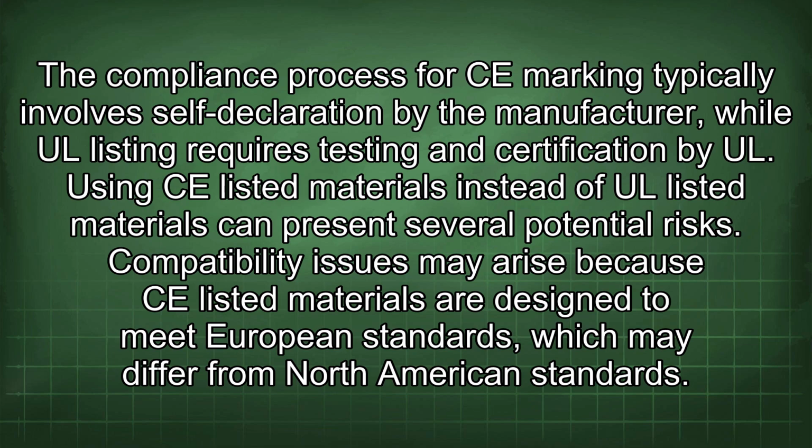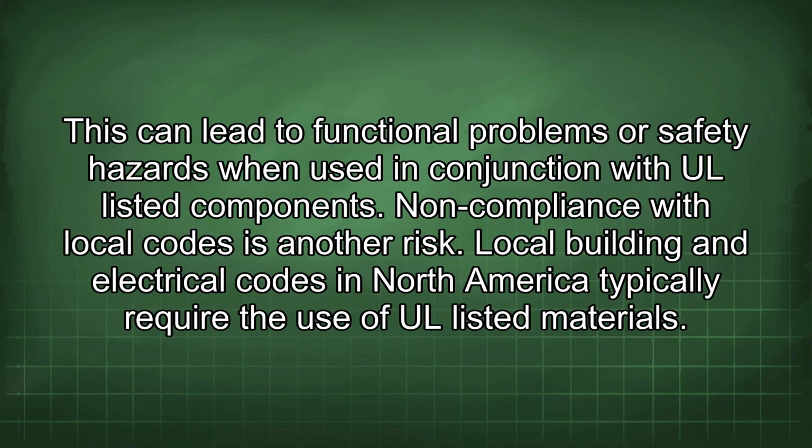Using CE listed materials instead of UL listed materials can present several potential risks. Compatibility issues may arise because CE listed materials are designed to meet European standards, which may differ from North American standards. This can lead to functional problems or safety hazards when used in conjunction with UL listed components.